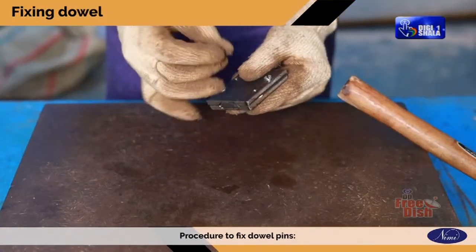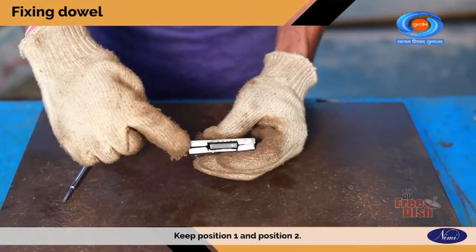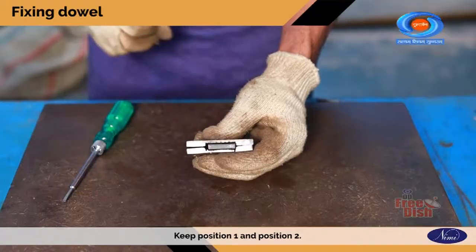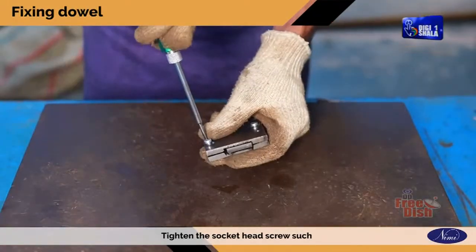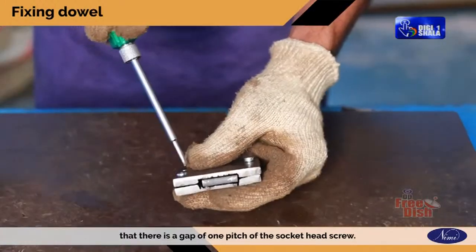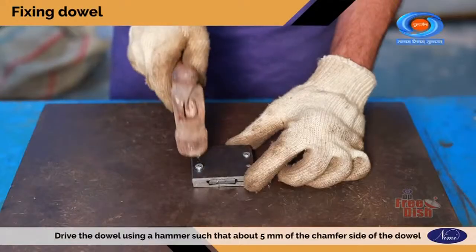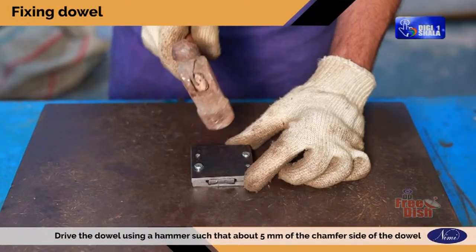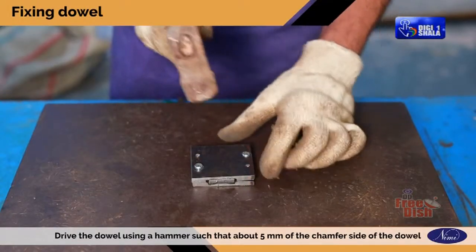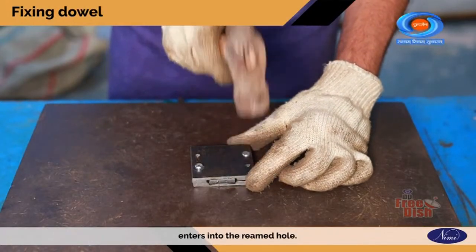Procedure to fix dowel pins. Keep position 1 and position 2. Tighten the socket head screw such that there is a gap of 1 pitch of the socket head screw. Drive the dowel using a hammer such that about 5 mm of the chamfer side of the dowel enters into the reamed hole.